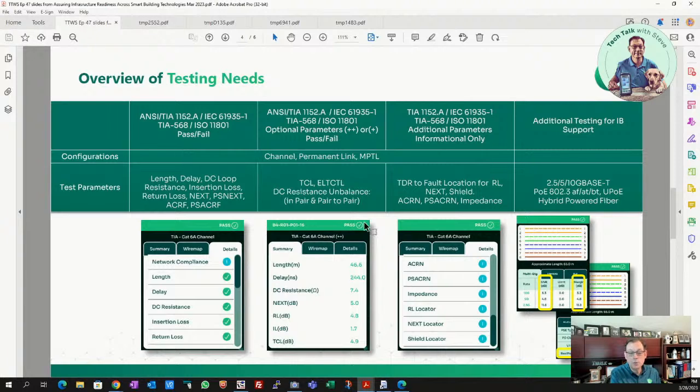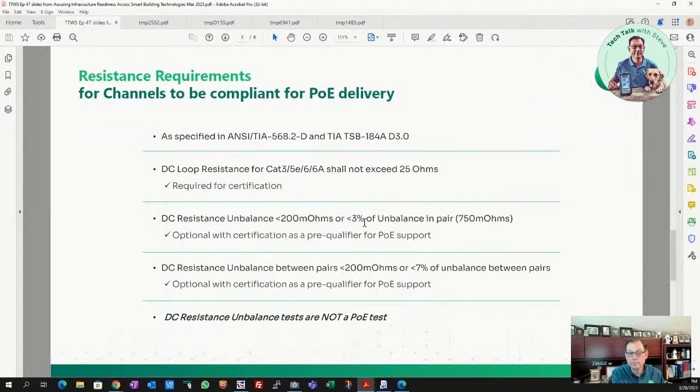And you want to have troubleshooting capabilities, which we will here in the network service assistant. You'll see that TDR trace to a return loss or crosstalk issue or a shield problem. And then, of course, being able to test the gigabit or multi-gigabit links for signal to noise ratio to make sure that you don't, in fact, have too much noise on there, and that you can get that speed at the endpoint.